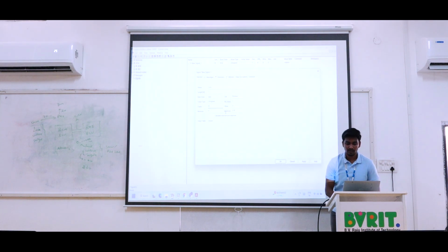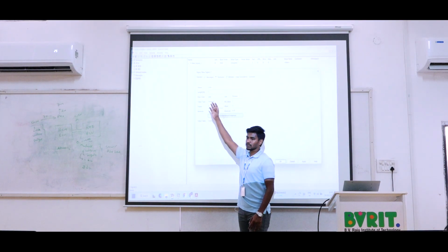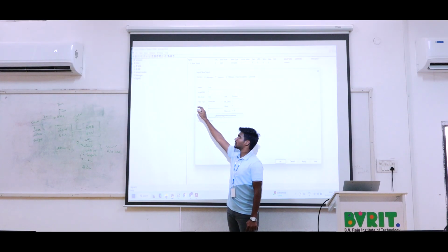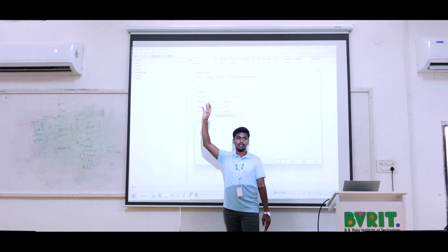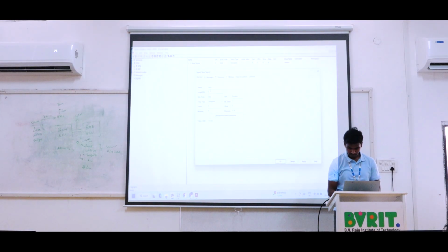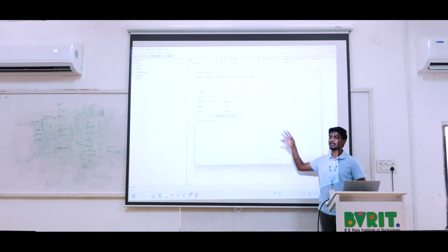So based on our calculations, suppose you have exceeding bits. For example, RPM goes up to 10,000, but we are going to take only 8 bits, and 8 bits is not sufficient for RPM. You can check this: with 8 bits the maximum value generated will be 255, but we need to compress 10,000 into the 8 bit range.